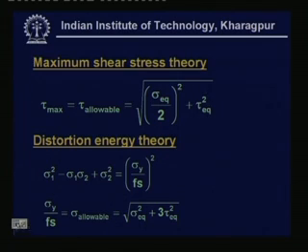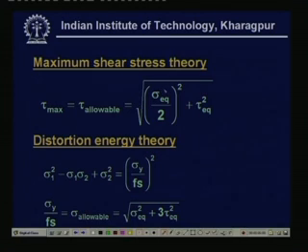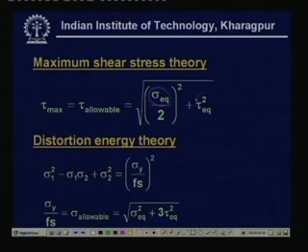It is needless to mention that once again this tau equivalent will contain all the terms of the stress amplitude, the mean stress and the material properties. So, once we write this expression in terms of tau equivalent and sigma equivalent, it contains all the design parameters I told you about in the earlier slide.